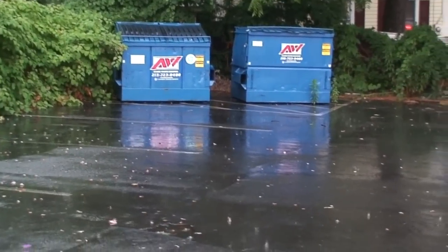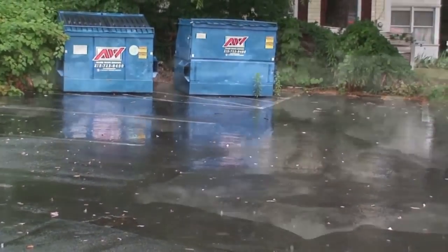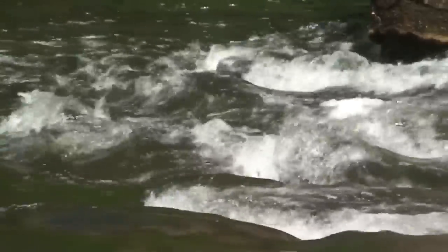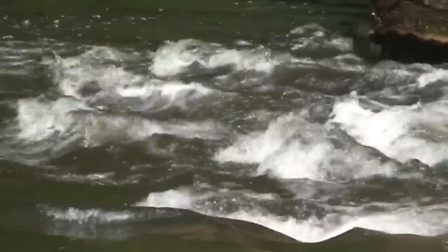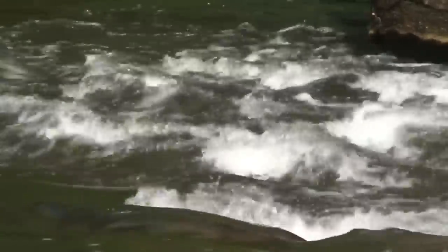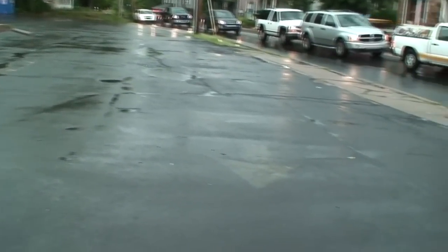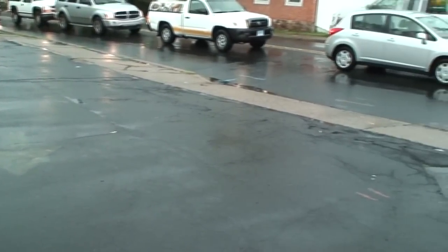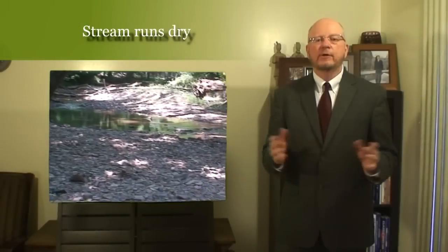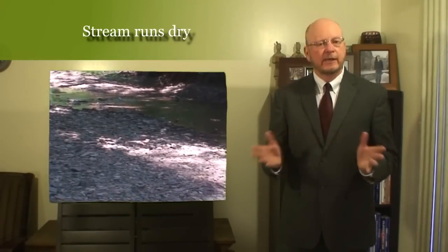Presently, for small storm events, the existing waterways are receiving stormwater runoff from built areas in short bursts of time, a few hours. Now, this is caused by the rapid storm runoff flowing from existing impervious pavement and building areas. After a couple of days, the stream dries up.